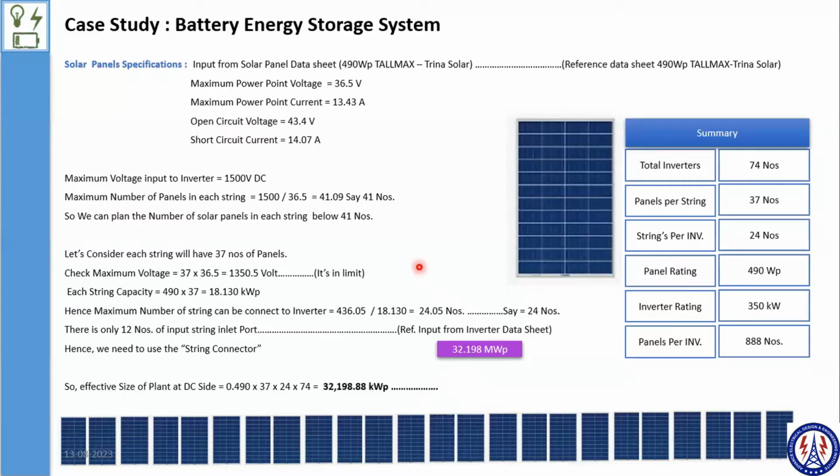And that's why your current capacity can be managed. If you reduce your 1500, let's say up to 1200, even in that scenario your capacity is managed. Got it? Yes. So this is how you can optimize your plant. Otherwise, you need to increase the number of inverters. Yes, it will be increased. So that's the scenario.